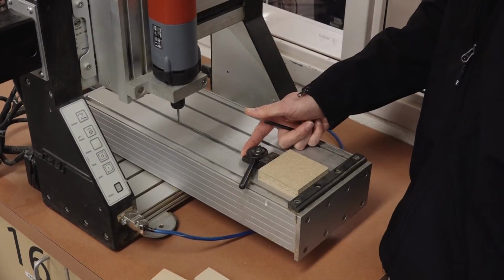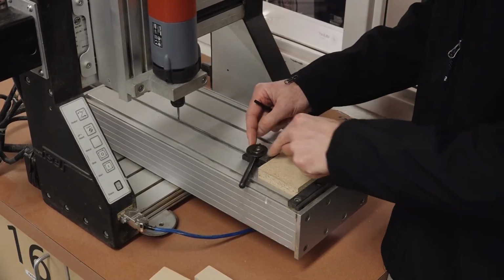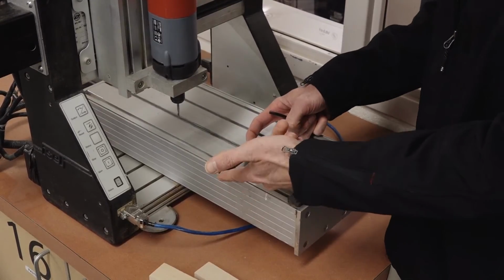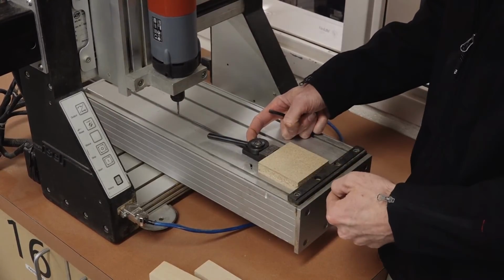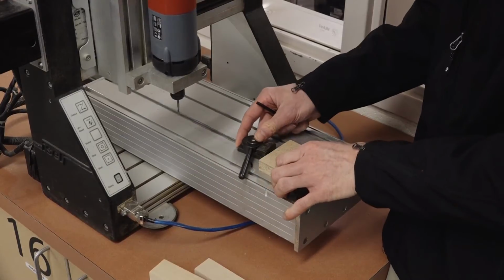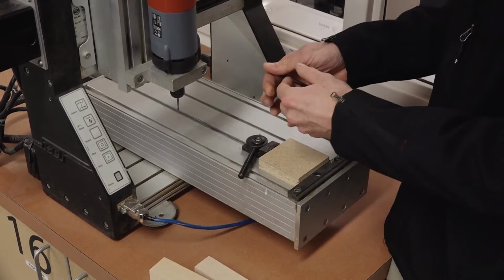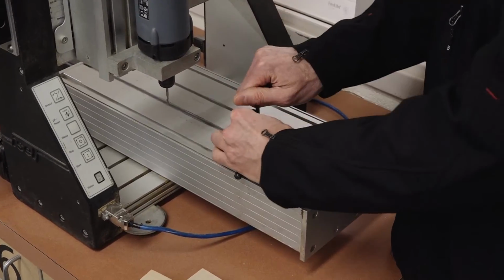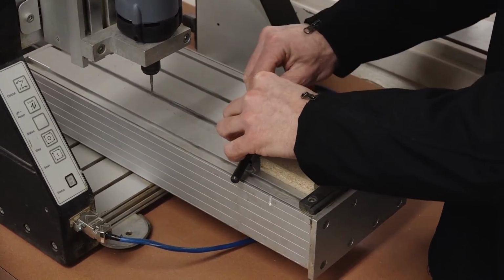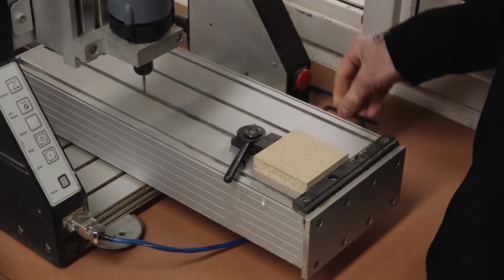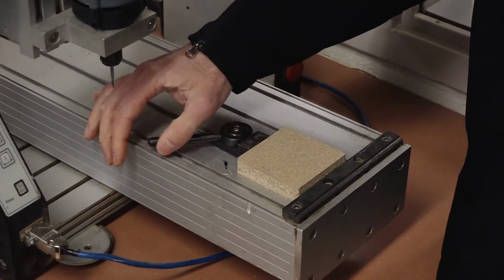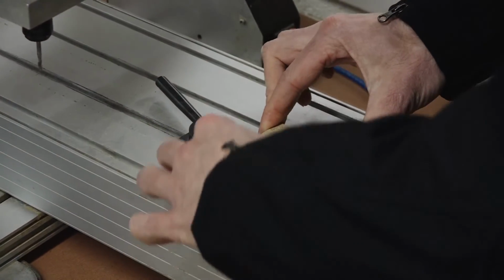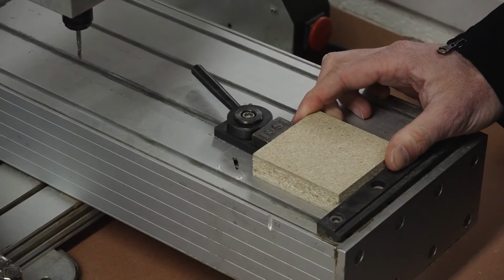to my left. This is an eccentric shaft, so when I tighten it, once I've tightened it in place, moving this lever will tighten it further. Okay? So you butt it up there with a handle like this, then you take the Allen wrench and you tighten it. You don't have to really wrench on it, but just make it firm. And then you tighten this, and if you can move the whole machine, you're in good shape.